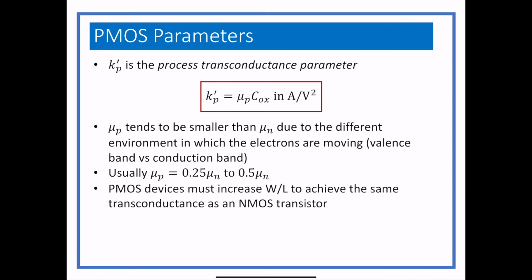So PMOS devices actually have to be bigger. They have to have a larger width to length ratio to get the same effect. So they can have a disadvantage in that respect. But this is what they're good for.